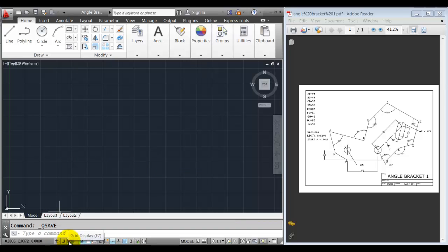Now, there are several tools at the bottom left corner in the status bar. I choose to turn off the grid display and actually everything else except for 3 icons. The 5th icon is polar tracking, which will give us our straight lines and some of our angle settings. Object snaps to snap onto existing geometric positions of an object, although we won't be using this one for this detail. I like to keep that one on.